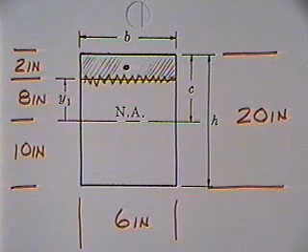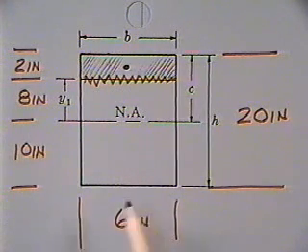There will be some shearing stresses at that section. He says, well, calculate how much shearing stress there will be at that level on the beam so I can go out and buy a can of glue that says 60 psi strength glue or 200 psi shear stress glue. You know, they got glues of different strength. So here's what I calculate.